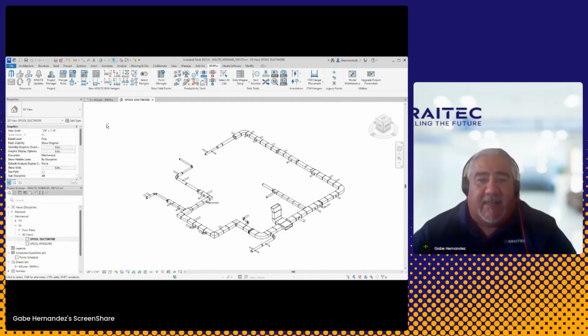Again, just to quickly go over what I was talking about, I've got my Manage Spools tool. Right here's the Create Spools command and the Breakup command for breaking up spools, again, to start over if necessary. I've got Merge and I've got Divide Spools. Here are the color coding tools, where I can add colors to spools and color services. I can strip the colors, and then I can show what's been spooled in a view and what hasn't. So again, kind of pick up where I left off the day before.